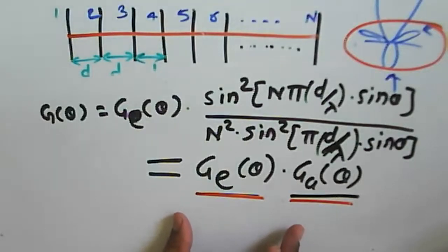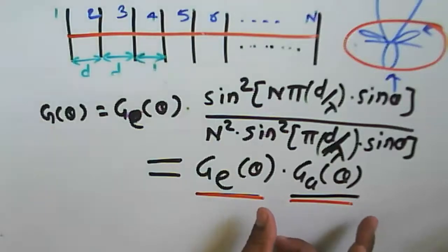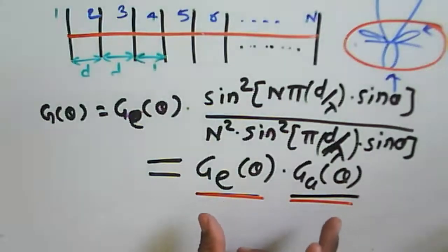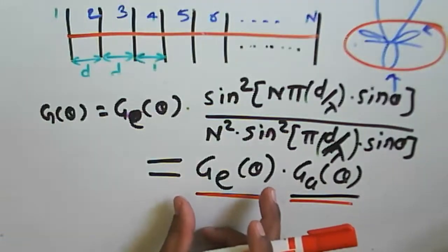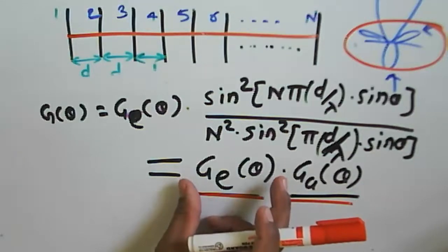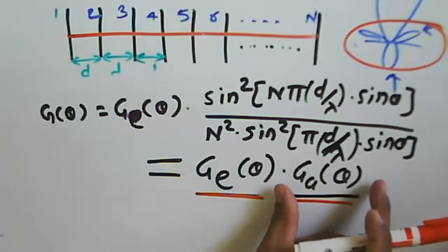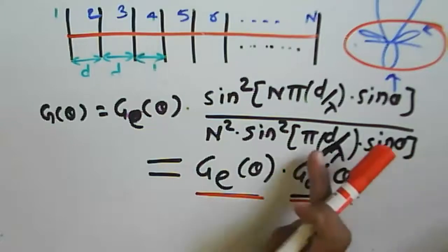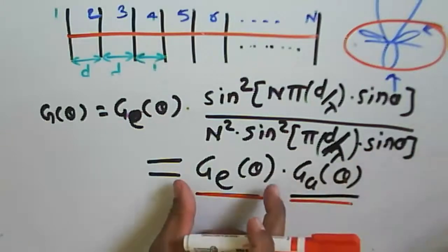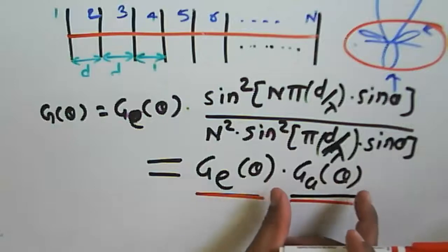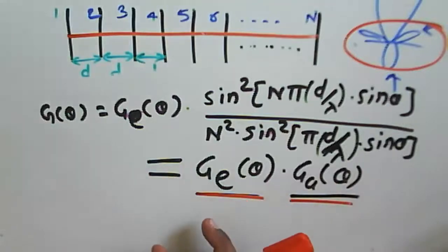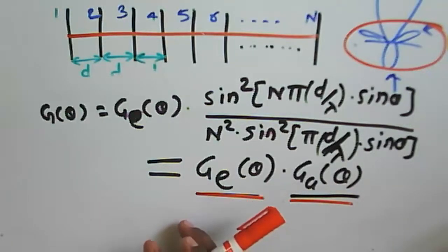It consists of an element factor as well as the array factor. Every element has some particular radiation, so the radiation from the array is generally called the space factor and the element factor. Element factor into space factor gives the total radiation of the antenna.